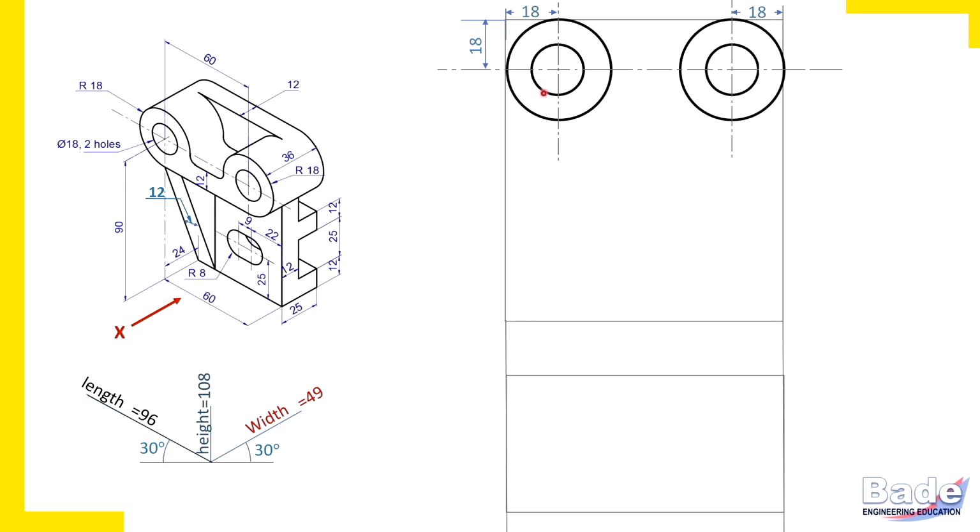So draw concentric circles. So inner circles represent opening of these two holes. When depth of holes is not given, we should assume through holes. So these holes are through holes. But right now in the front view, we can just see the opening of the hole.